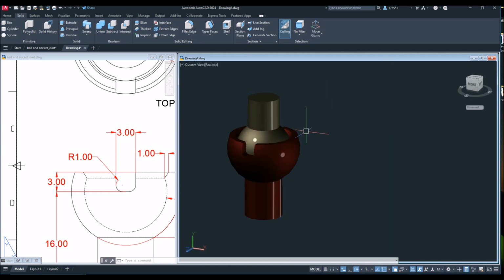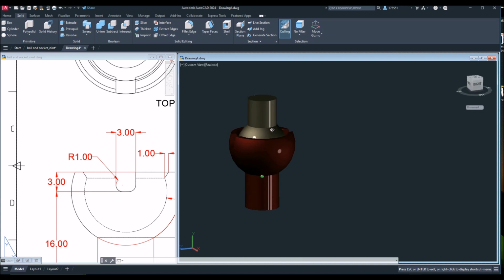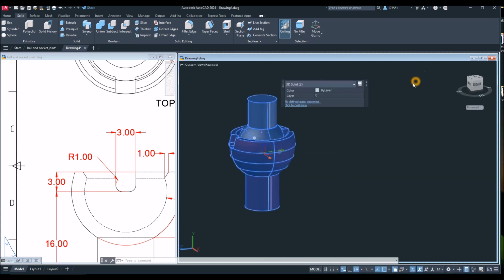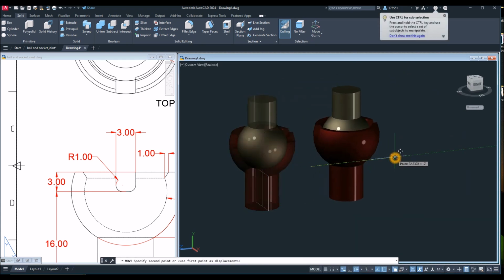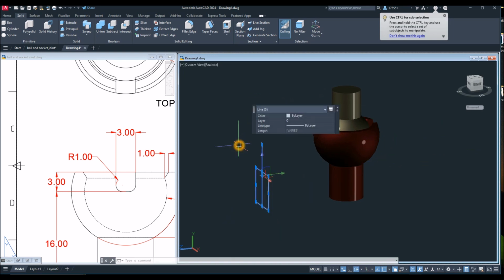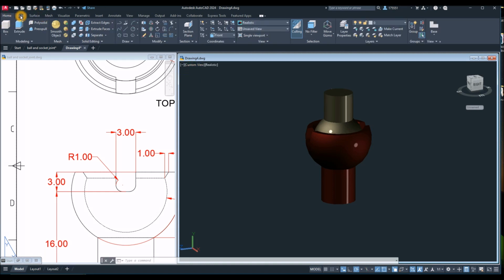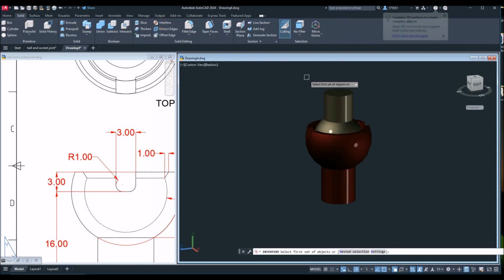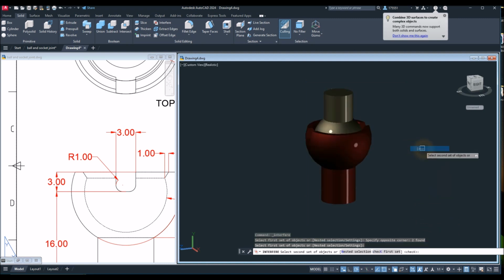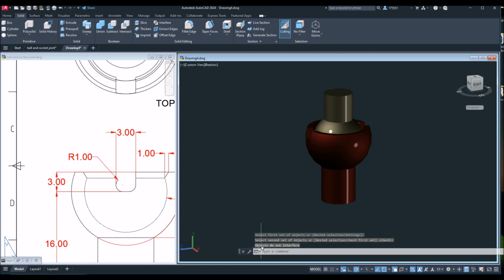All right, what else? I'm just gonna move these two objects so I could get rid of the construction lines. And then I'm gonna check if this object is interfering. So go to home, oh no, solid, interfere. So inside the command prompt, you can find this text here saying objects do not interfere.